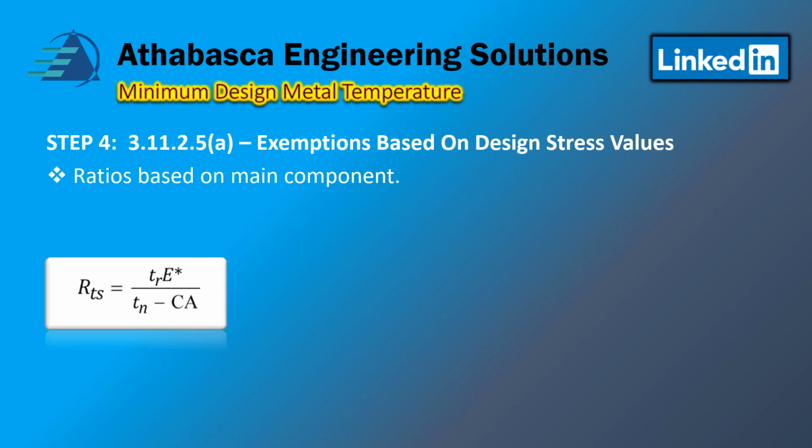You can use the relationship of the required thickness, which is based upon the pressure of the component, the required stress, over what's available. If you have a very small ratio, that means the part hasn't been stressed very much, and there's room, you can get some credit to reduce your MDMT.